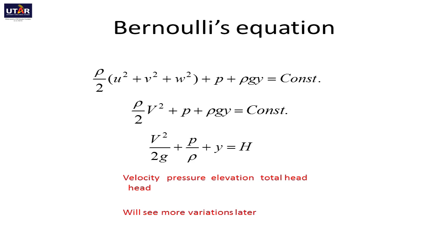This Bernoulli equation can be written in a few different forms. The third equation writes the constant as variable h. That allows an approximate relation for flows that do not strictly satisfy the assumption of zero vorticity or irrotationality, which is satisfied in inviscid flow with negligible viscosity and negligible effect of turbulence.